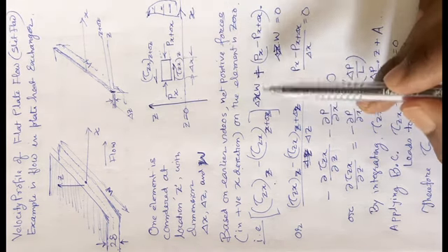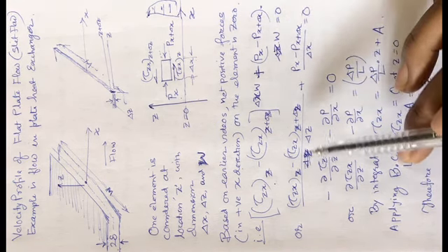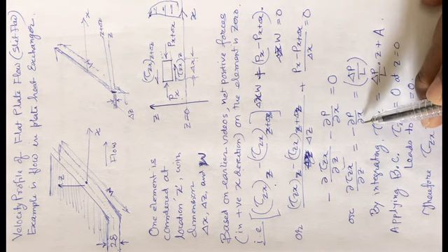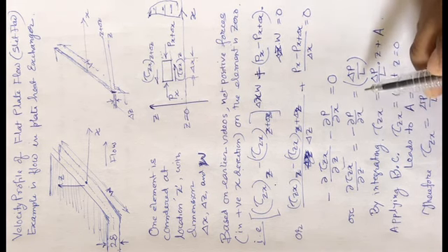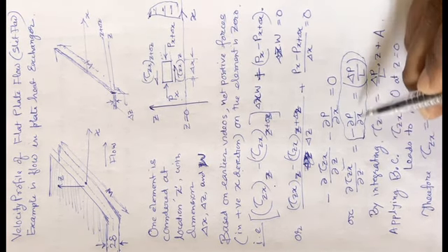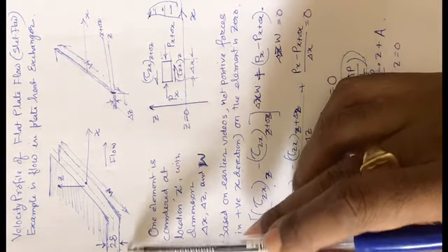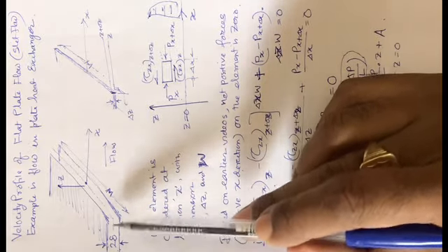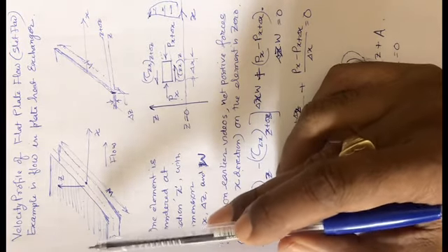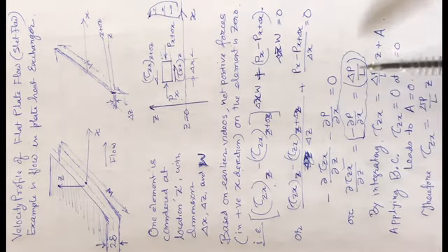Okay, so now on both sides you divide by a factor called delta x into delta z into W, then you are going to get this particular expression: del tau zx by del z equals minus del p by del x. Now this is what you call the hydraulic gradient or pressure gradient causing the fluid to flow. This same thing we sum up as delta p by L, where L is the length of the passage through which the fluid is flowing. The left hand side's pressure is quite high, maybe because you are maintaining hydraulic head by some overhead tank or by use of some pump. Okay, so delta p by L.